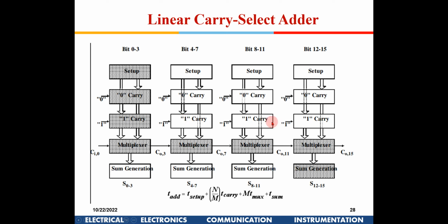So all these 4 computations complete in parallel and are available to the mux. Now the only task is to select the appropriate mux output, because all these verticals are doing calculations without waiting for any input from the preceding stage. So depending on the mux, the correct carry will be selected.